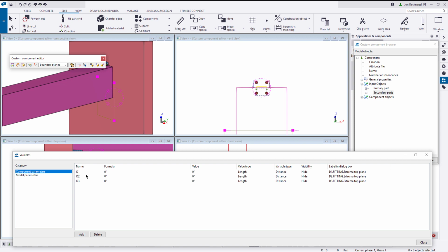You can see with that single click, because there's 3 handles here, I've just created 3 bindings. I've basically told all 3 of these handles to always equal 0 now, because these handles are touching the face, so that distance in my y-axis was 0. So all 3 of those will be 0.